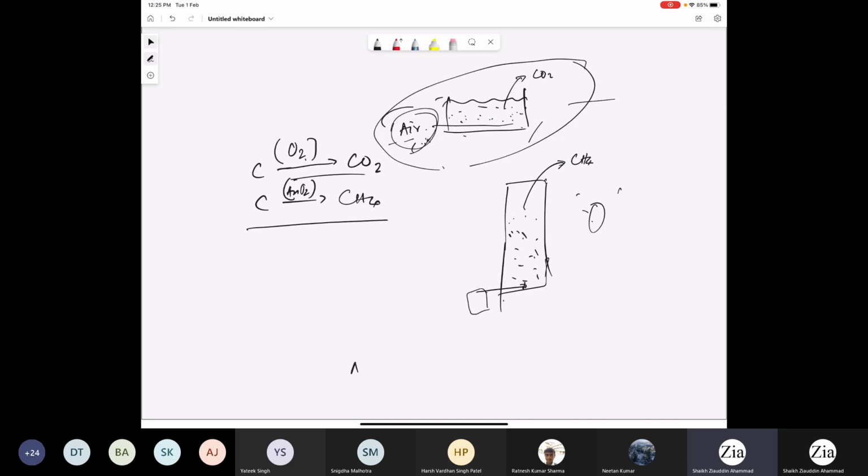Now, in this particular case, if you have high carbon, then all the granules, because we have mentioned four different reactions: hydrolysis, acidogenesis, acetogenesis, and methanogenesis. All four reactions are in series, so they are dependent on the earlier group. The synergistic activity of these different bacterial groups will help you get carbon to methane.